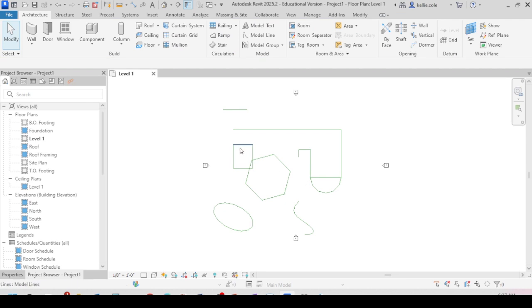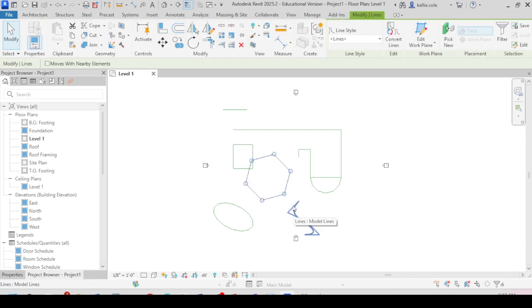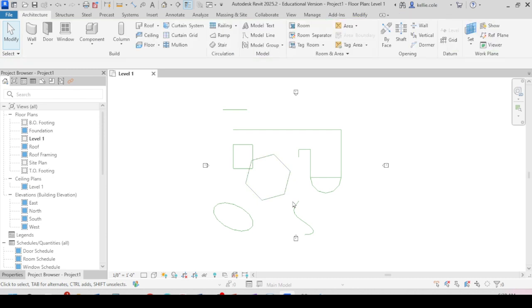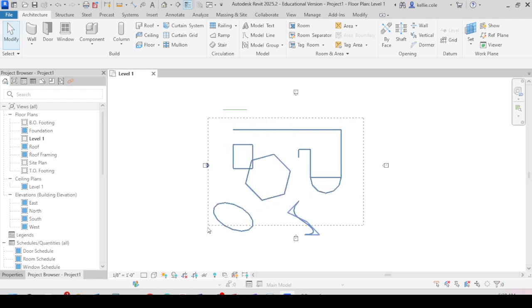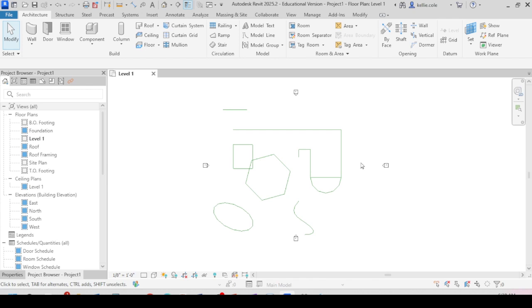Any box that you drag left to right, so I'm clicking, dragging, and letting go, selects anything within that entity. If, on the other hand, I draw a box in the opposite direction, so I'll click, drag left, anything that box intersects with, it doesn't have to be the entire object, will be selected. So experiment with that for a second.